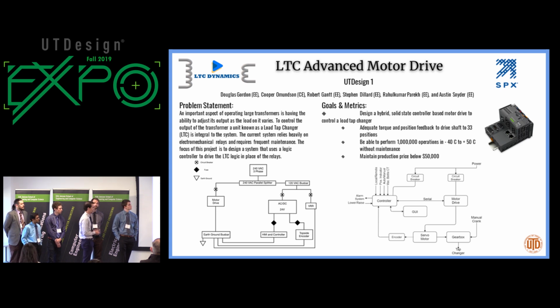One could be that the vacuum bottles did not discharge properly, and so it needs to send out an alarm for that. Another could be that the shaft encoder and the servo encoder do not agree with each other, so then it will output another alarm to one of our HMI panels that's connected via Ethernet.